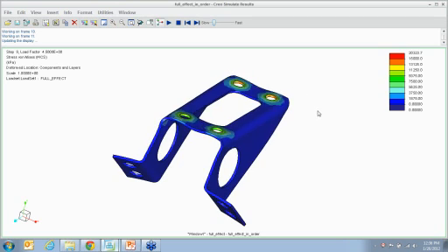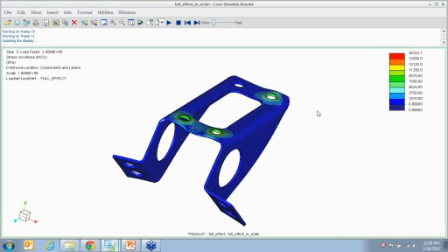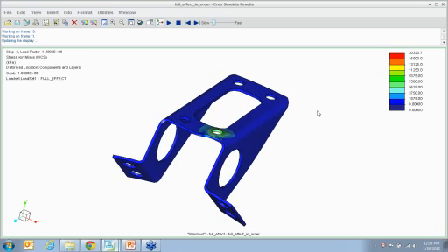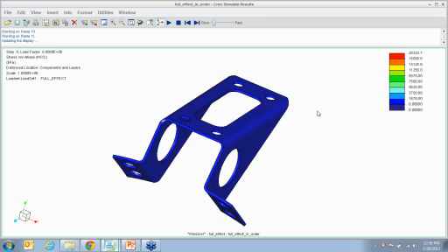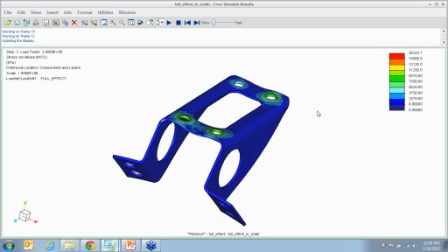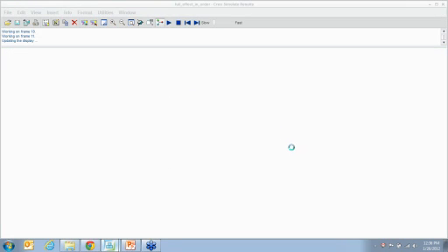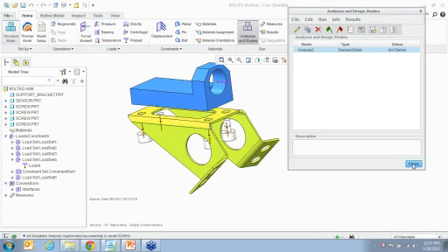So what it gives you is you can control during an analysis if the load runs from the start to the end of it, or does it start 2 seconds after the analysis and end 2 seconds before the analysis ends. So you can control the time through which the load is acting in an analysis, which gives you a much more realistic representation of what's happening in real life, right?